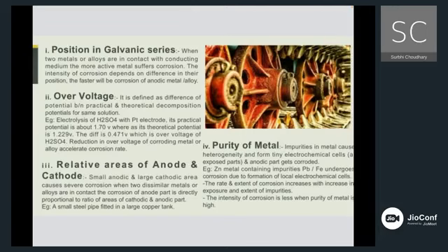This is because the more reactive metal acts as anode in the electrochemical cell which forms at the metal surface. At the anode oxidation takes place, and the metal gives electrons to the oxygen and is converted into metal oxide there. When metal oxide is formed, that means corrosion takes place, that means disintegration of the metal takes place. This is the ultimate reason why the highly reactive metal is more prone to corrosion as compared to the less reactive one.